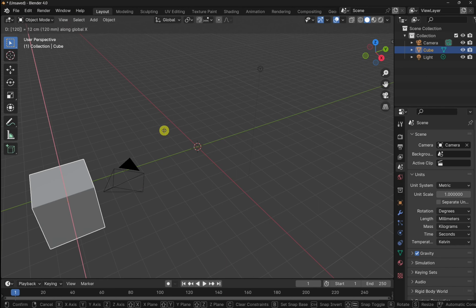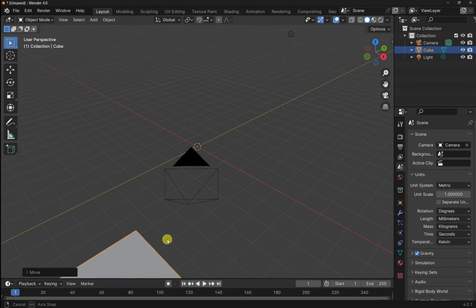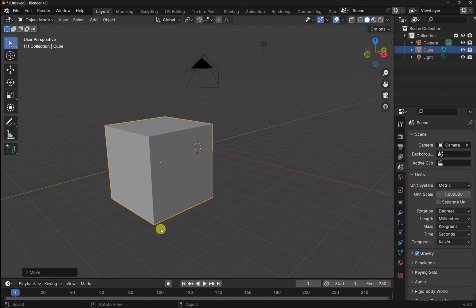And I can type in to the X axis whatever I want as well. So I'm going to type in 123. Let's move it to 123. Let's delete that. Hit delete on the keyboard. If you look at the top left, 300. Move that 300 millimeters. Go for 3000. And we just click to accept. So that's moved that way, 3000 millimeters.